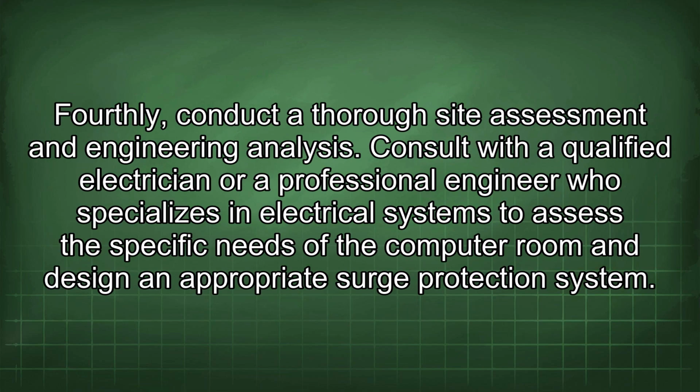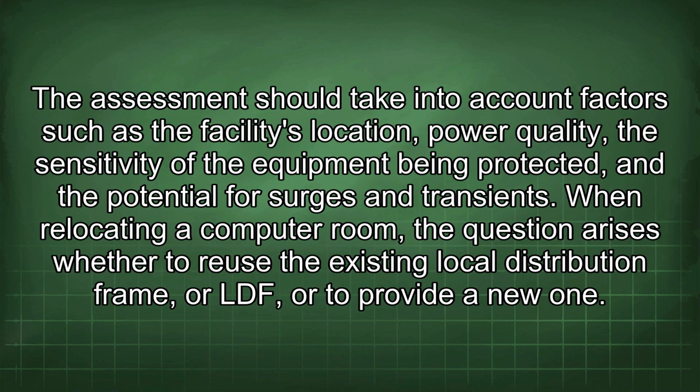Fourthly, conduct a thorough site assessment and engineering analysis. Consult with a qualified electrician or a professional engineer who specializes in electrical systems to assess the specific needs of the computer room and design an appropriate surge protection system. The assessment should take into account factors such as the facility's location, power quality, the sensitivity of the equipment being protected, and the potential for surges and transients.